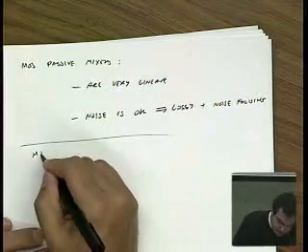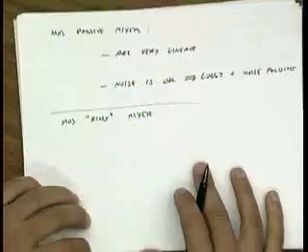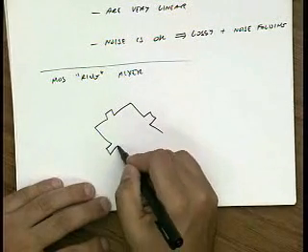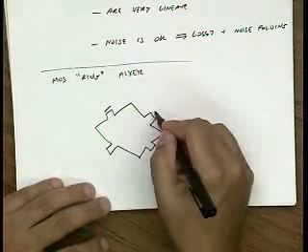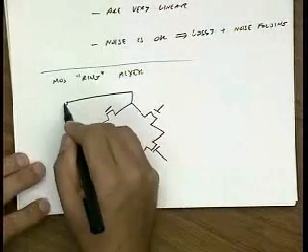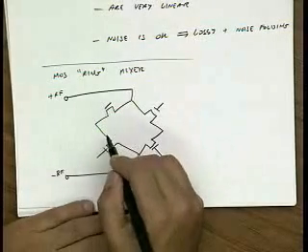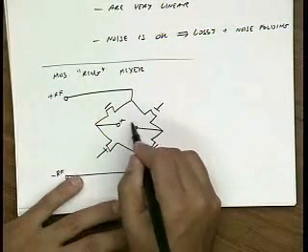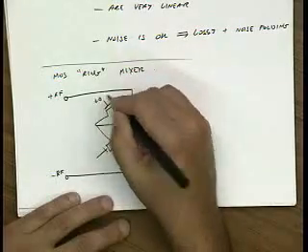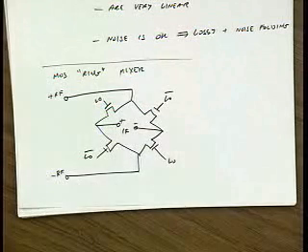Well, actually it's also pretty common to do a ring style mixer. And a ring mixer looks like this. It's 4 transistors in a ring. And what I'm going to do is inject a differential RF signal here, or if you like, a floating RF signal here. I'm going to take my IF signal here, again a floating IF, and then I'm going to apply my LO here, and LO bar here and here. Okay?